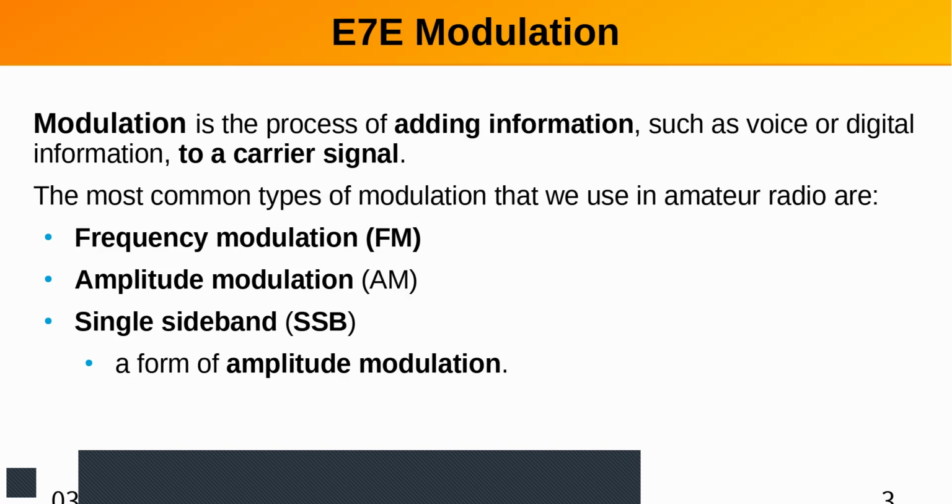We have amplitude modulation where we vary the amplitude and we keep the frequency constant. In FM modulation, we try to keep the amplitude constant and vary the frequency. FM receivers don't like varying amplitude. That's why they have a thing called a limiter circuit to try to make it a constant amplitude. Otherwise the discriminator circuit doesn't work right. So you have a limiter before the discriminator.